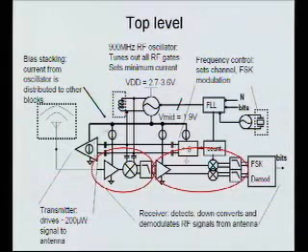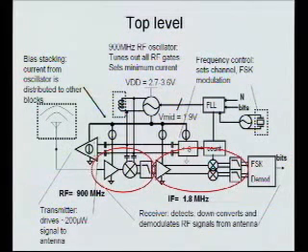All right, so let's go to the receiver. Just to remind us of frequencies, I implemented a low IF receiver, not a direct conversion, for some reasons I'll get into in a moment. The frequencies were 900 megahertz and then an IF of about 1.8 megahertz. So a very low IF, but not true direct conversion. What you can see over here is actually a conversion finally to baseband.